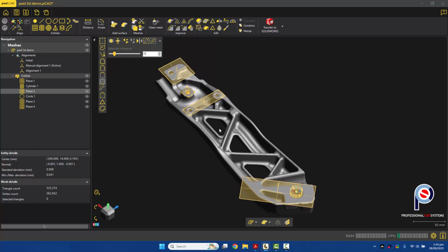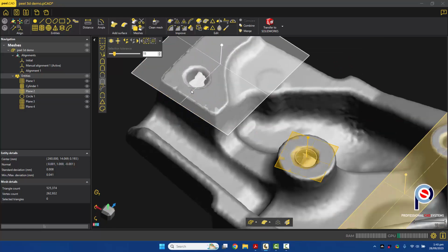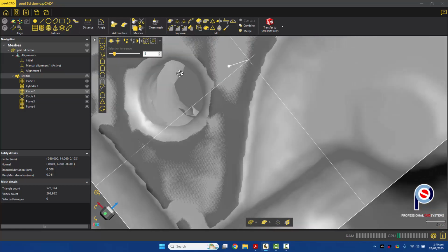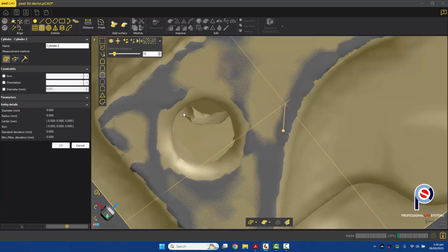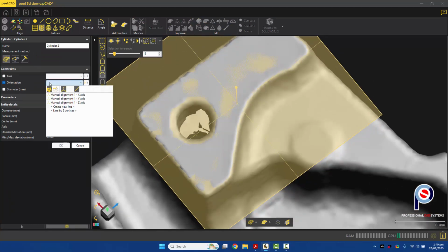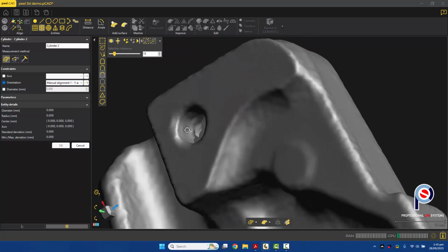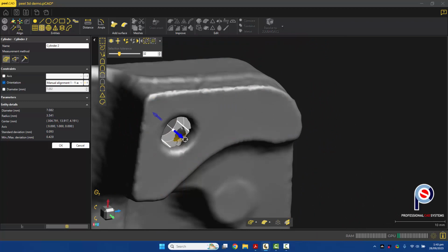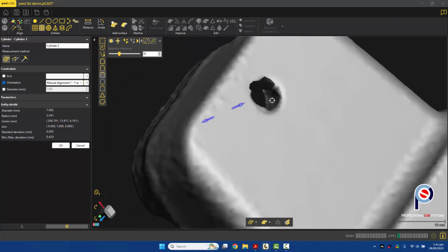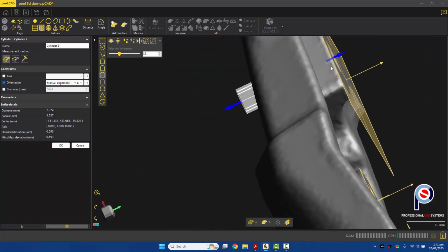Okay, so now that I've got those, I now need to extract the entities that I want. So this is actually a cylinder because it continues on past here. I'm going to get the cylinder and make its orientation normal to the y-axis. So I'm going to hold control and click on the cylinder there. Again, increase the selection tolerance, grab a little bit more data, then jump to the other side of the hole and get a little bit more. And then I can just make that cylinder go out past each end.